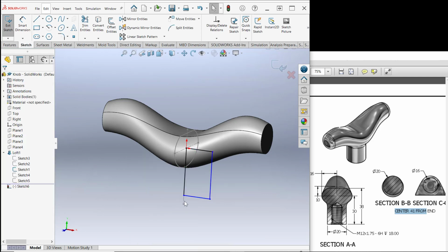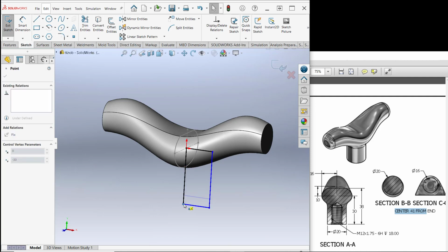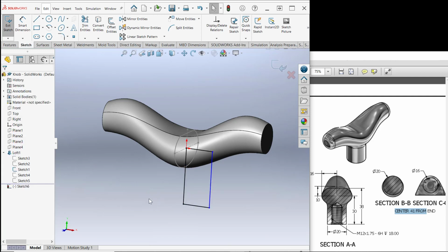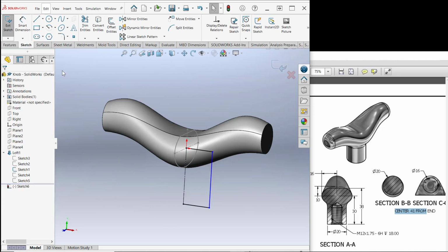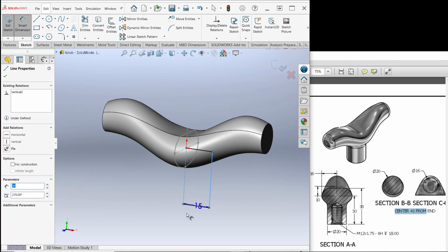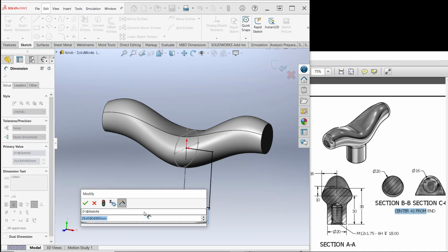And then I'm going to drag this point and hope that it'll snap to the end of that line. If it doesn't snap, they're just at a coincident constraint. I'm going to change this line to a center line or construction line. And then I'm going to dimension, so I see from here to here is 20, so I'm going to dimension from that center line over to this line, get on this side of the center line, put in the diameter of 20.